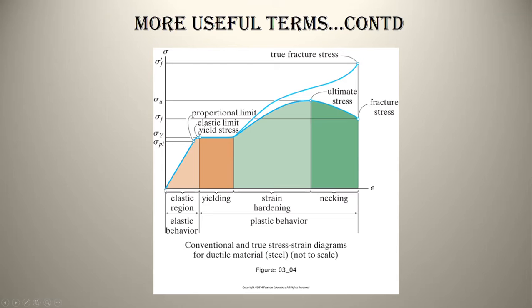If you see, you start from zero stress, zero strain. You start loading, you follow a straight line up to proportional limit, PL. Beyond proportional limit, there is a yield point. And beyond yield point, without increasing any stress, the strain keeps increasing. This is where the material just yields. It yields for a certain time. This is what you see there. And this is the yield strength.